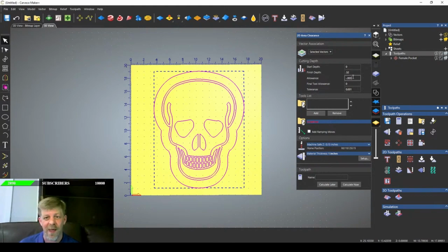0.007. I've had one go, and I've actually had them a little looser and needed like 0.002. But generally 0.003 when I'm doing inlays is about the correct amount of space that you need. Clamping pressure is essential in these, so you want to make sure that you can really clamp down on that.